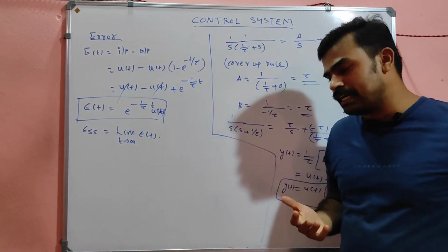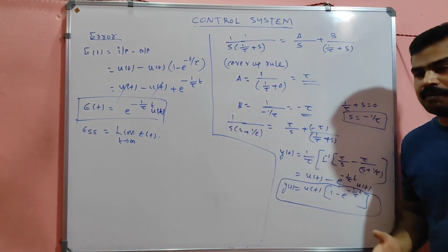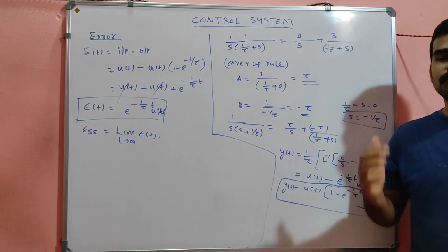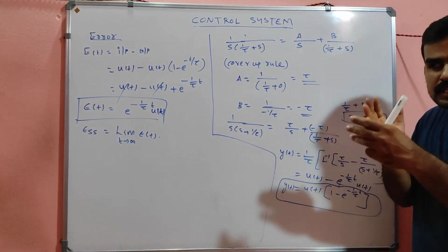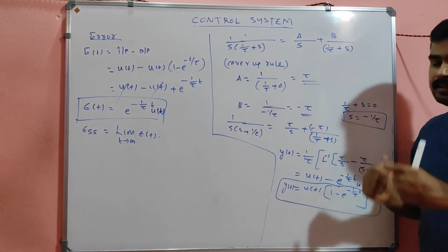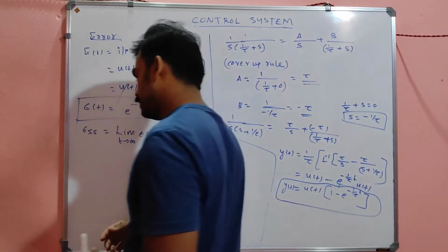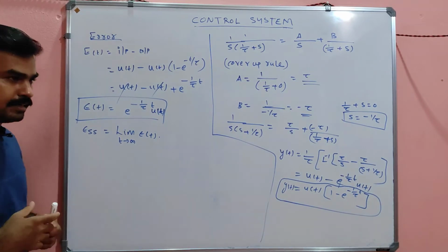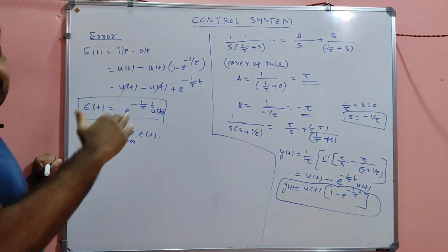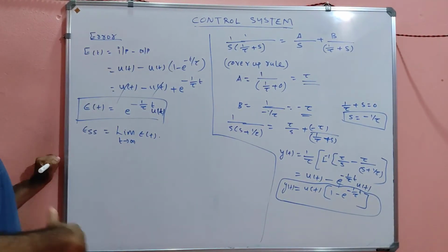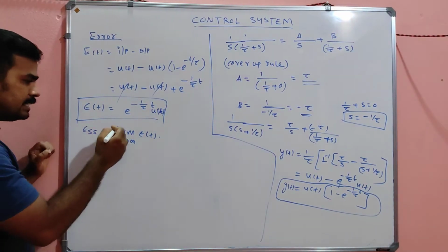But we have to check after some time, right? After 1 hour of operation or 2 hours of operation, whether the system still contains that error. We have to monitor now. That is why it is called the steady state error. That means after the steady state is attained, after a very long duration, the steady state error will be seen.